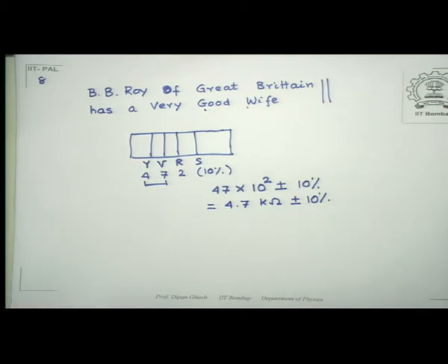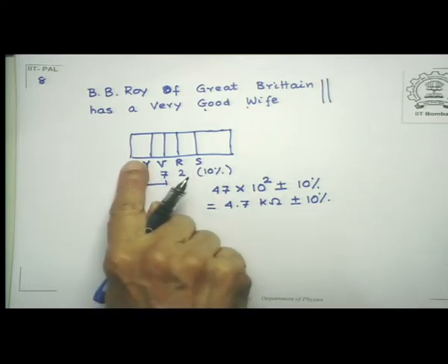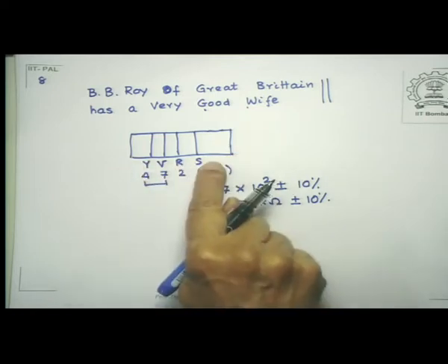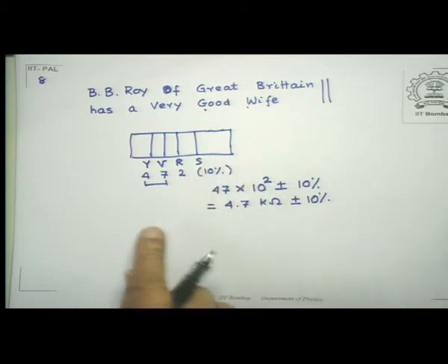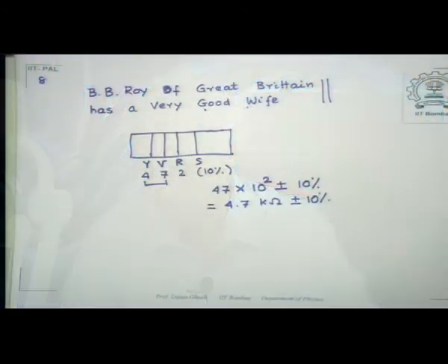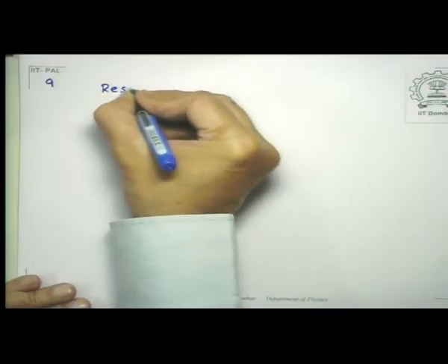Occasionally, but not in your labs, you might find a resistor with 5 bands, in which case the same principle is true, but the first 3 figures represent the significant figures. So this will be useful if you want to represent higher values of resistances. Having said that, I did mention that the resistance of a sample depends upon temperature. Let's see why and how.